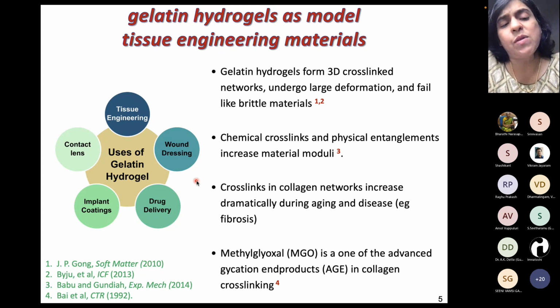Some of the main problems with using gelatin are that it's highly variable, because we can't control the length of the polymeric chains that we obtain from the powder gelatin that we acquire. We can introduce chemical crosslinks and stabilize the gel, but we also can't use too much of the chemical crosslinks, which is typically glutaraldehyde, because it's a cytotoxic material.